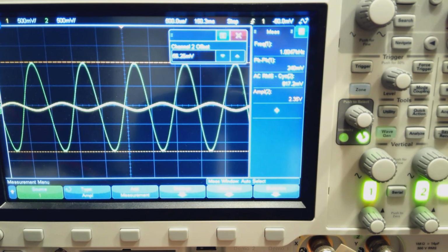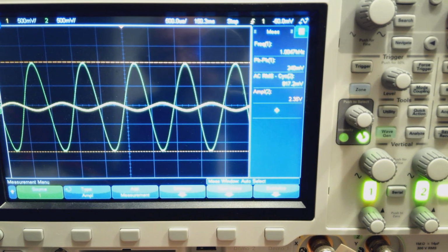I ask you to do this with Circuit Maker, just to give you a little bit of frame of reference. Again, with 200 millivolts in, my output is roughly 2.35 volts. So those are some of the values you should be looking for in the experiment, so the gain will be close to 10. In the experiment, I then ask you to increase the input signal level.